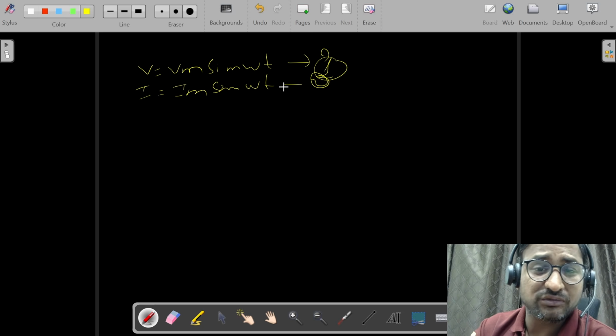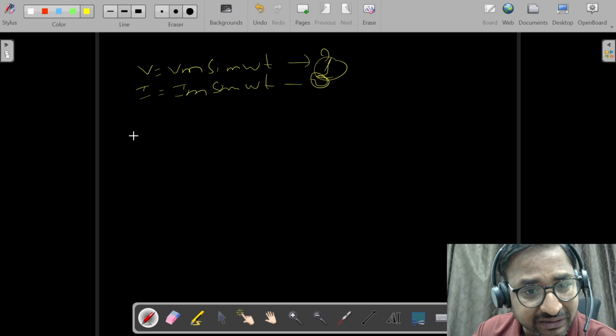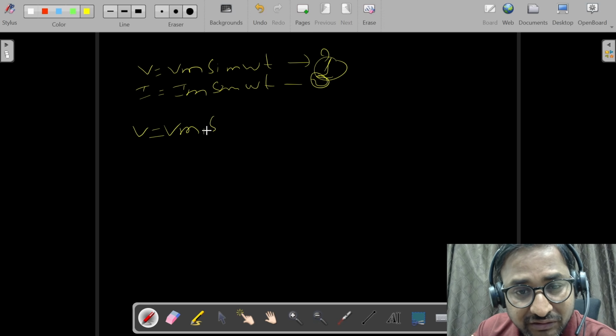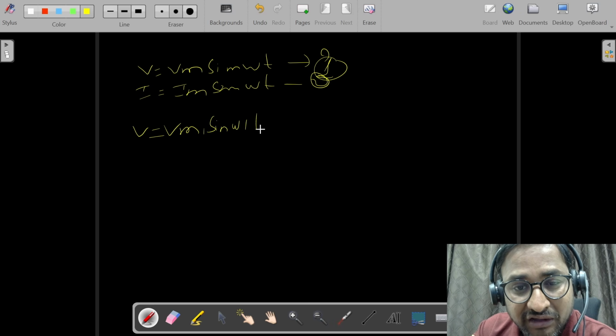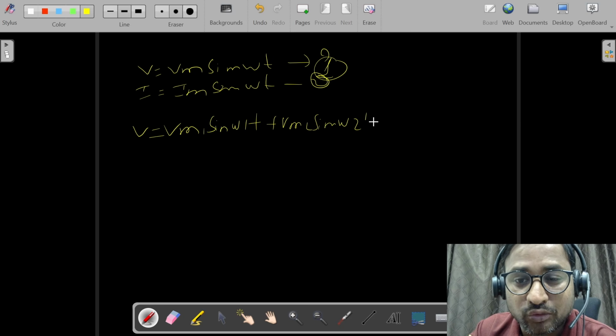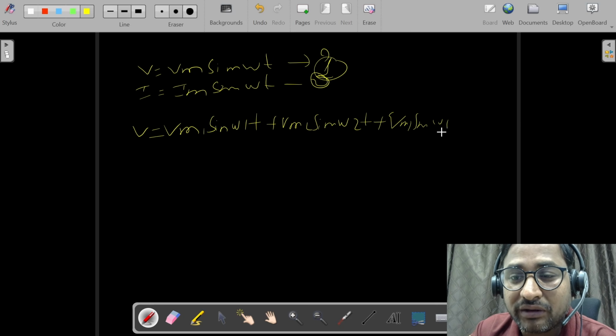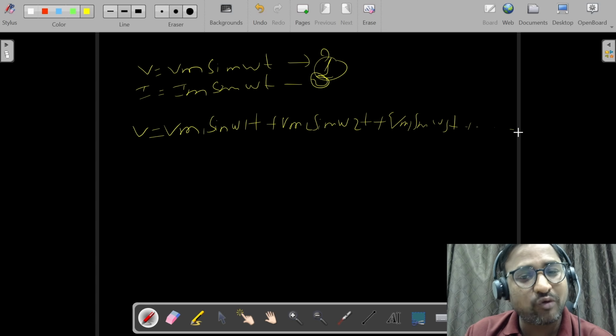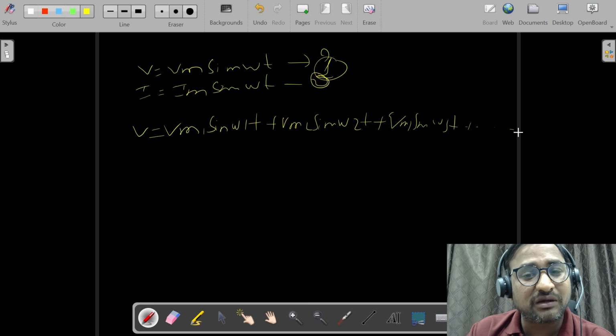After the production of harmonics, we can represent it in mathematical form as V is equal to Vm1 sin omega 1t plus Vm2 sin omega 2t plus Vm3 sin omega 3t plus, continuing in this way, with omega 1, omega 2, omega 3, omega 4. In this way, multiple frequencies are produced in the signal.